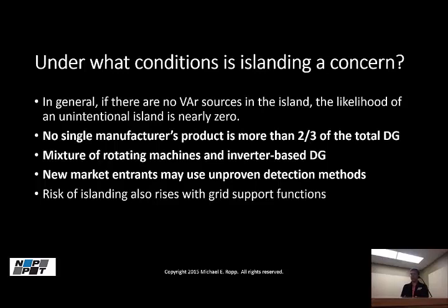What happens, as I mentioned before, is that when the island forms, the inverters are cruising along producing their output current, but then the voltage will jump to the new phase angle because the load is inductive. If there's no VAR source, then the inverter will start speeding up its frequency to catch up. Of course, the frequency goes up. That kicks the anti-islanding in, and out she goes. So if you don't have a VAR source, there will be a frequency deviation that could be detected, and it's not going to be an issue.